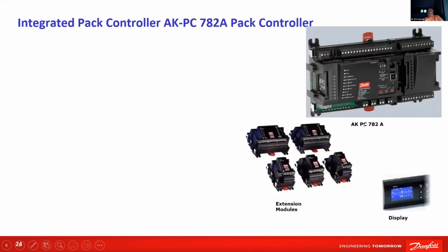Now, the controller I'm showing is AKPC 782A. This is one of the ones which you also use for the ejector. This controller will take care of controlling the entire high side equipment and the intermediate pressure equipment, but it doesn't take care of the evaporator. For the evaporator, you need another controller. At best, we can give some feeling of the evaporator into this, but the controller doesn't monitor the evaporator. It also has a small display, but invariably while using, you need a laptop or a monitor and some software to monitor or set things. And it also requires skills. It's not complicated, but it's a dedicated Danfoss tool.